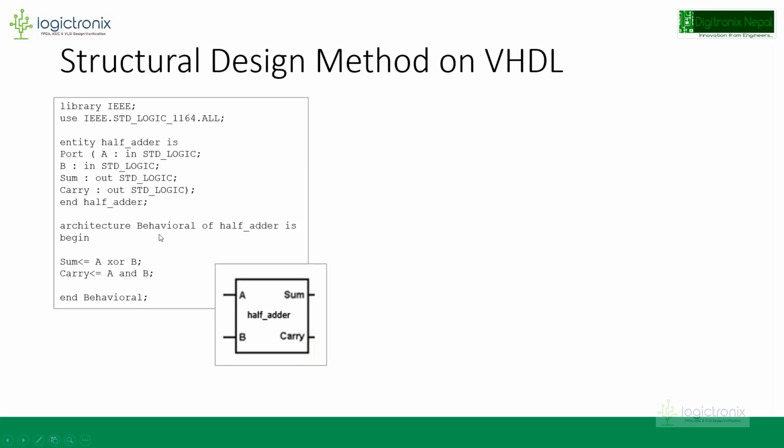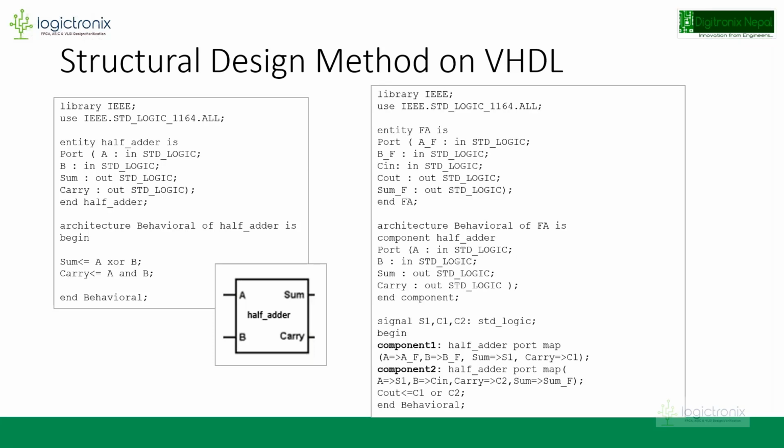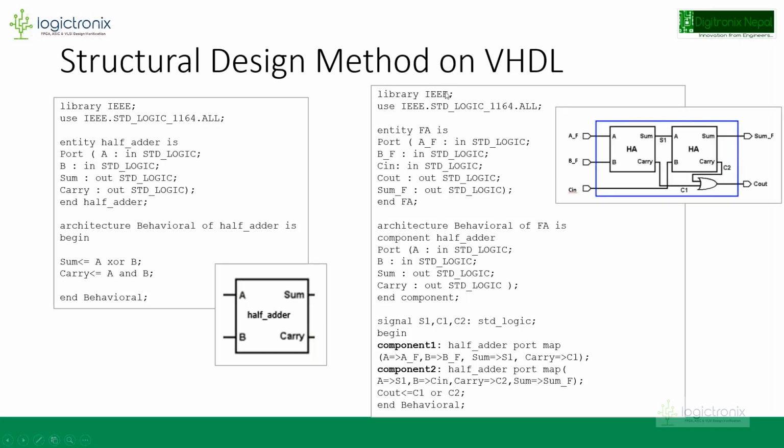So this is the basics of the half adder. We are not talking specifically about the half adder. Actually, we are going to utilize this half adder for the full adder design. So let's see the full adder implementation here. We just want to call this half adder module. We just represented the half adder in a box or block, and we want to call it inside a full adder module. Then we have to have a similar structure of writing VHDL programs. So we can see here the block design of the full adder where we want to have the half adder.